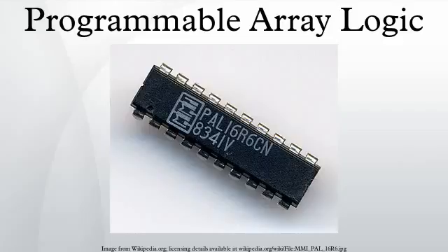This fixed output structure often frustrated designers attempting to optimize the utility of PAL devices because output structures of different types were often required by their applications. So, in June 1983 AMD introduced the 22V10, a 24-pin device with 10 output logic macrocells. Each macrocell could be configured by the user to be combinational or registered, active high or active low.